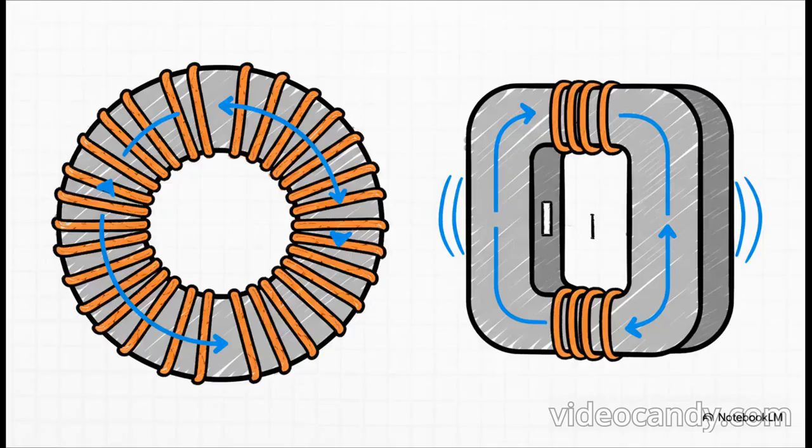And it's not just the material. The shape of that core plays a huge role too. A toroidal or donut-shaped core is super efficient because its magnetic field is almost completely trapped inside the core itself. Then you've got other shapes, like an E-core, which can be designed with a tiny air gap to stop the core from getting overwhelmed or magnetically saturated at high currents.